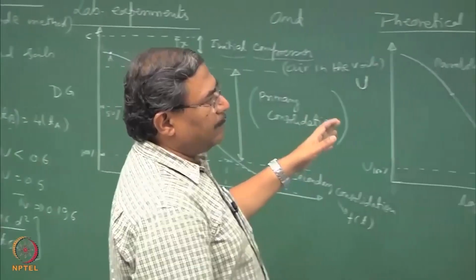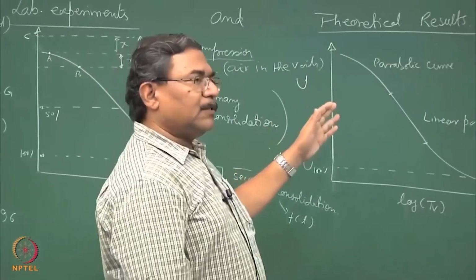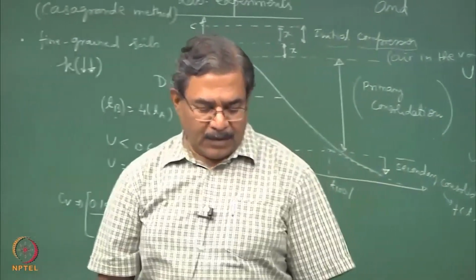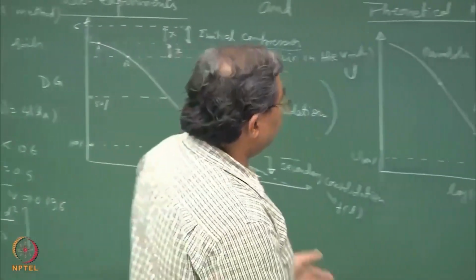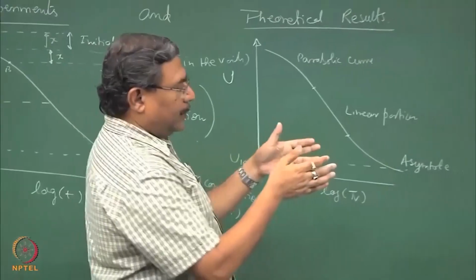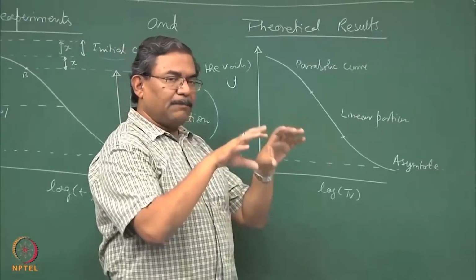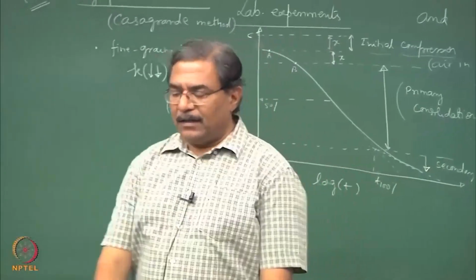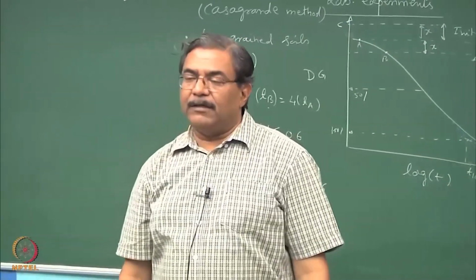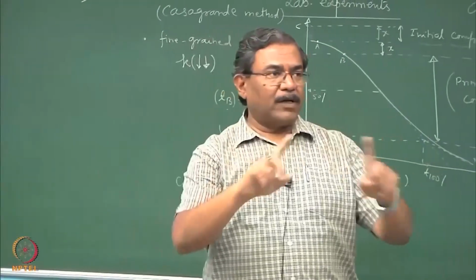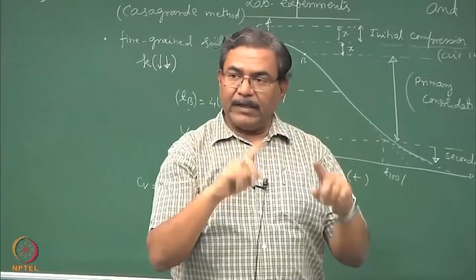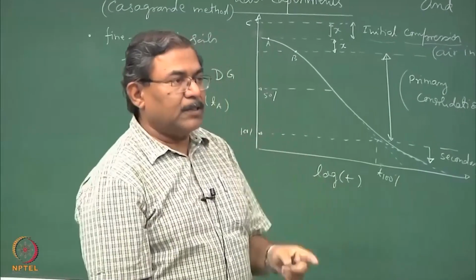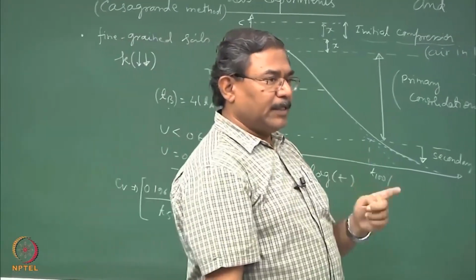Very rarely it so happens that one dimensional consolidation is going to be valid in the real life. If you remember, the basic premise here was that you have taken a steel ring in which the sample has been contained, and then you are applying load from one side. It is not a very practical situation in field, because you do not have rigid boundaries confining the soil mass. So, truly speaking, the consolidation is three dimensional in nature.